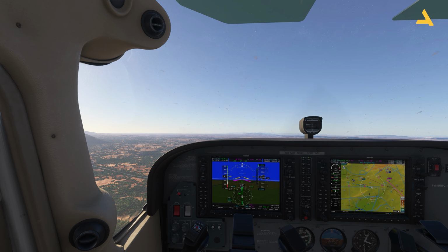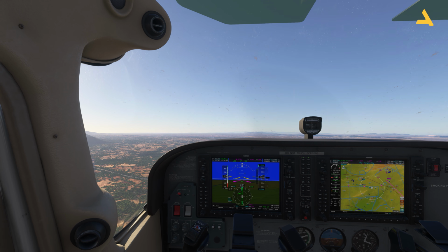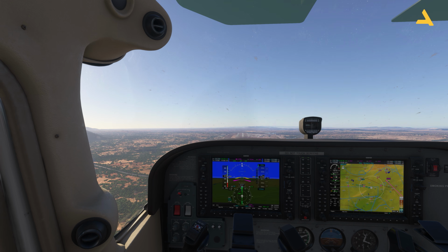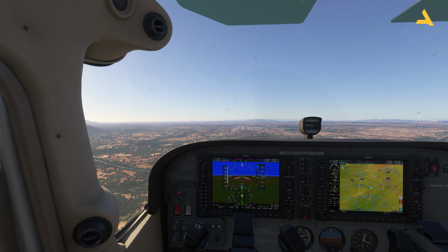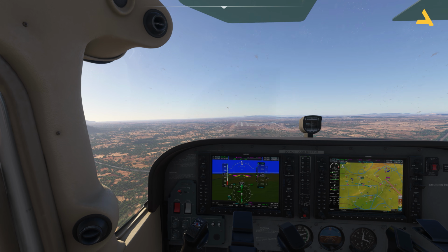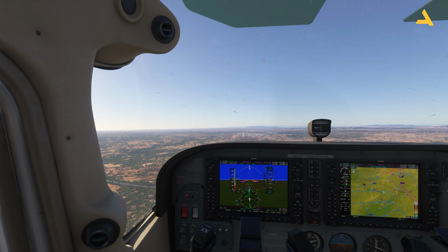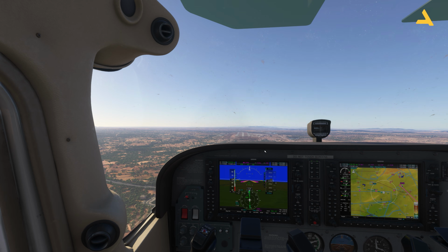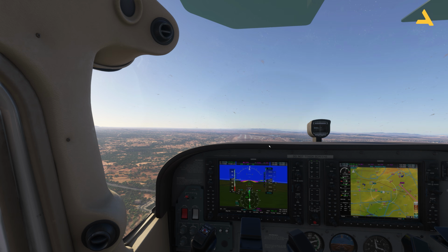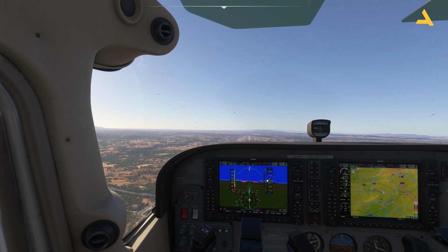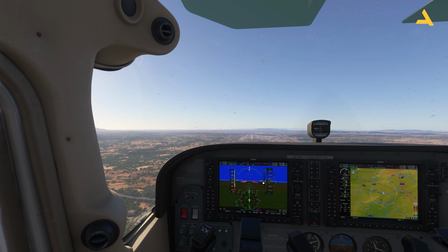Again, nose up, speed goes down, plane will stall, and full flaps. Because flaps are providing you lift but also providing drag. So full flaps, and let's keep the speed at 65 knots, and the plane is actually following the glide slope.